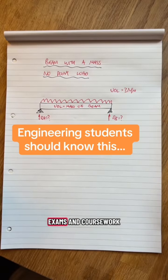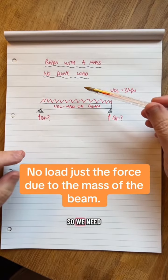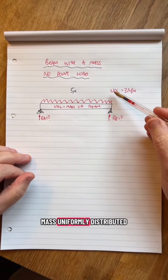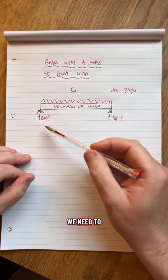Another beam question, very popular in exams and coursework in engineering, or A-levels, things like that. So this time, I've got a beam with a mass, no point load. So we need to work out what happens when you've got a UDL. Here's my beam. I'm going to give it a length of 5 meters. It's got a UDL, which is equivalent to the mass, uniformly distributed load of 3 newtons per meter. That means it's 3 newtons every meter. This thing's in balance, and we need to find RA and RB.